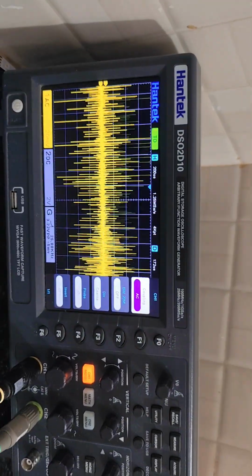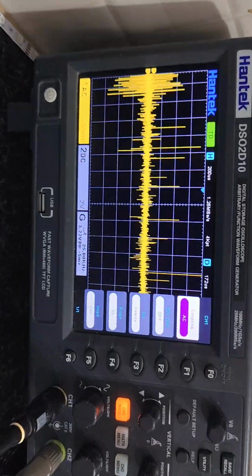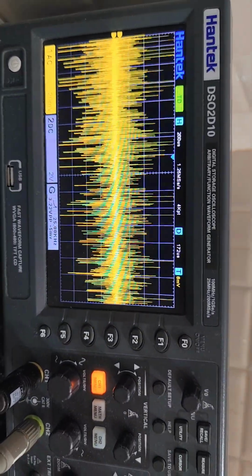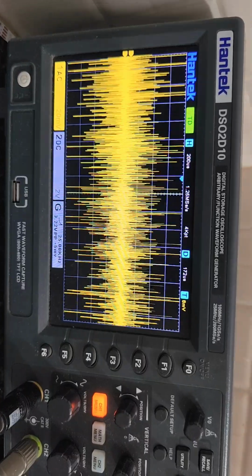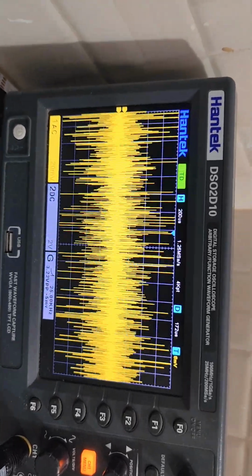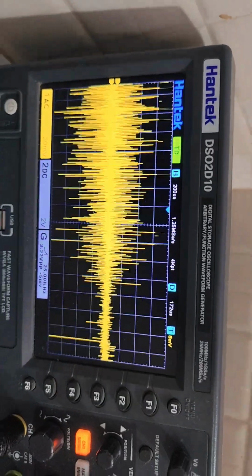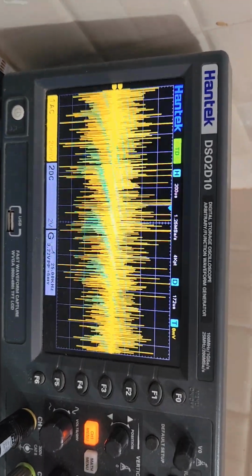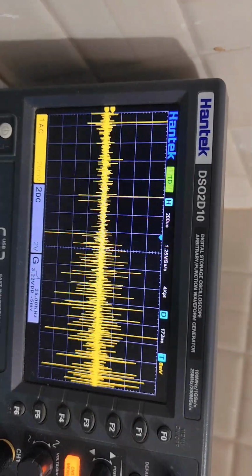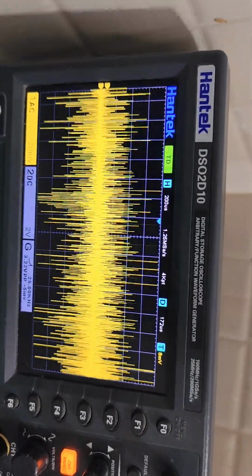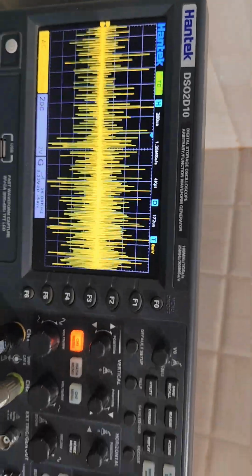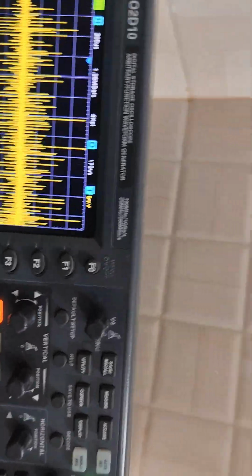That's why you need to get a proper power supply, because it might look outside like a good one, but once you look inside the power supply at what types of noise it's generating, this ripple depends upon the component types used inside the power supply. So you need to be careful about this. Yeah, so this was the topic of the video.